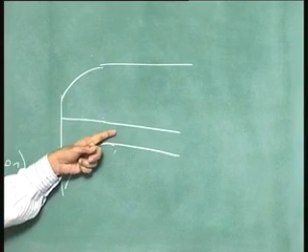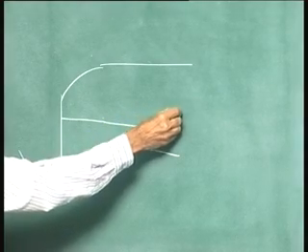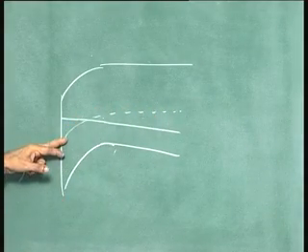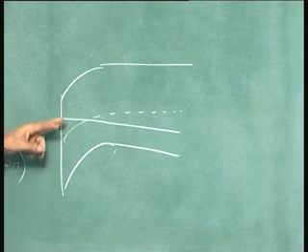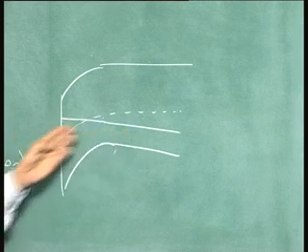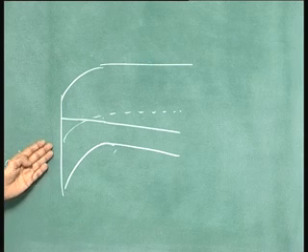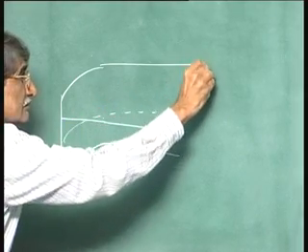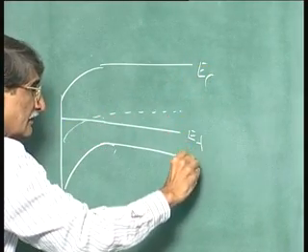This is the Fermi level and this is the intrinsic level. The more it bends down, the more it is towards n type, and more electrons will be there. In fact, if you move from here to here under thermal equilibrium conditions, you can plot the hole concentration and electron concentration. How will it be? This is EC, EF and EV.